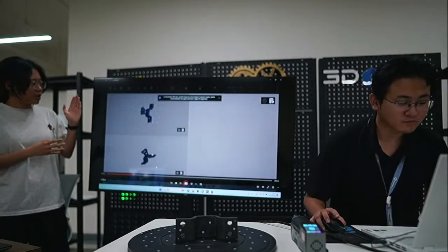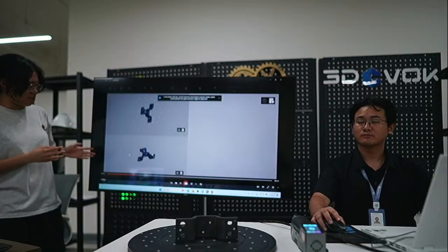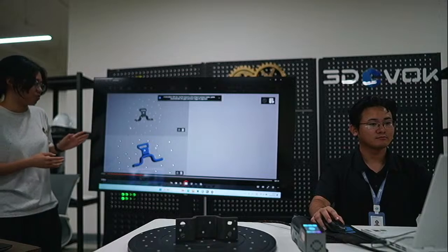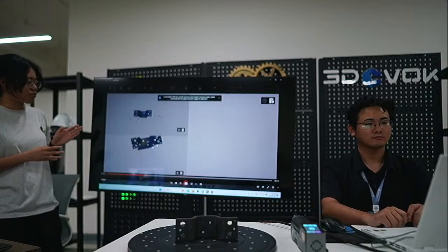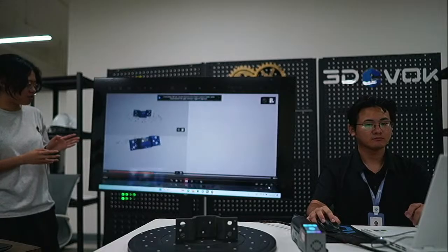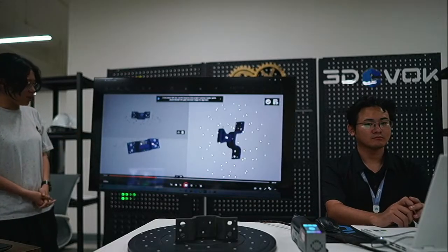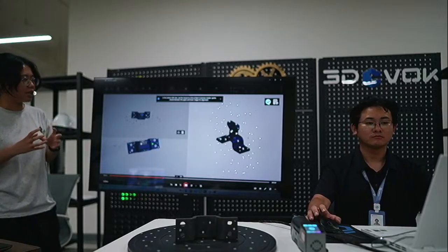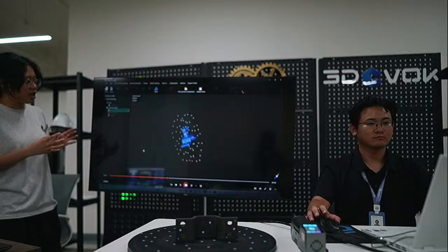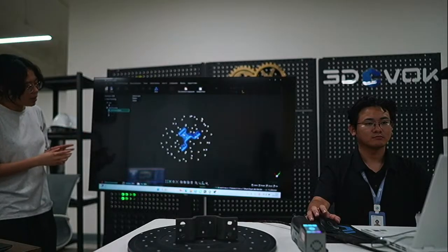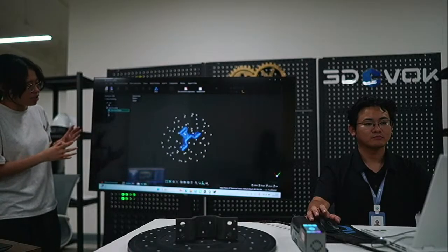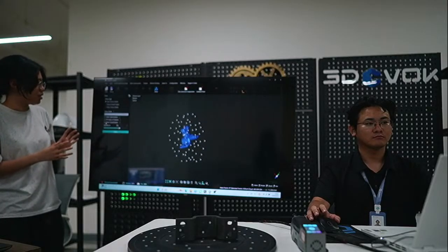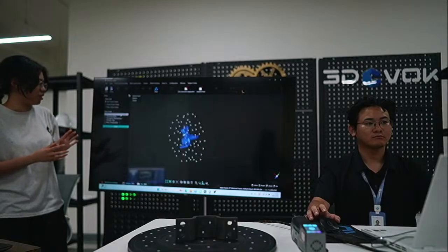And then we import the front part and the back part to choose the common markers on that industrial part, just to find at least 3 pairs of the common markers, so that we can align the models together. So you can see at the right side, we can combine the model and then click apply. The software will automatically do the combination, and then we can get a complete file. Choose the wrapping, and then we can generate a mesh model.